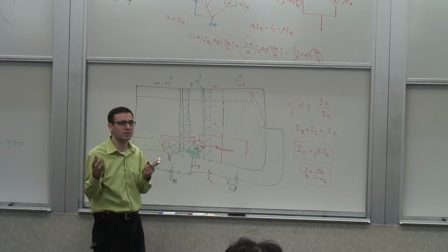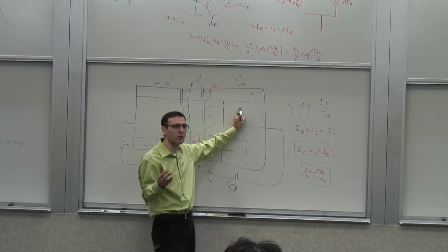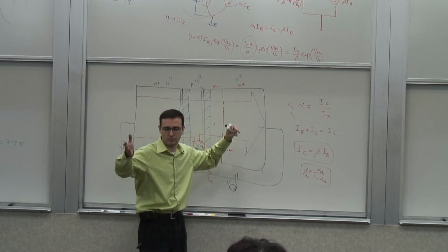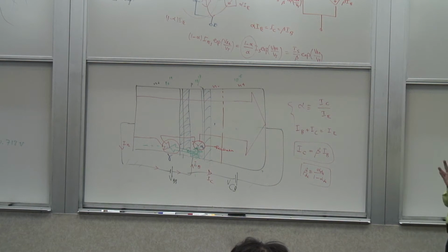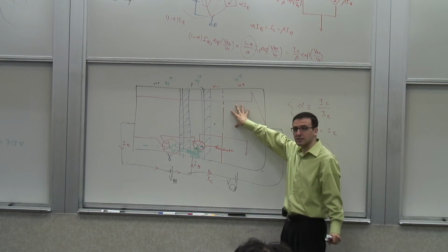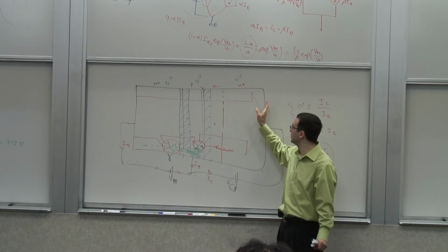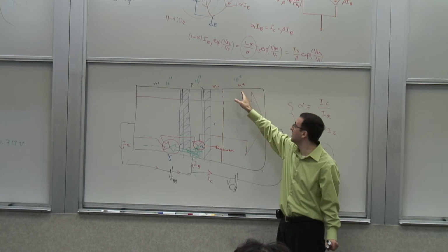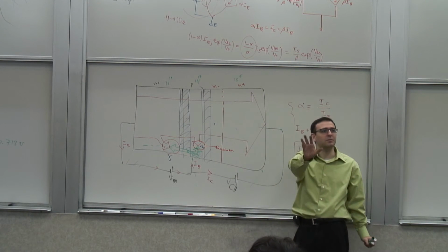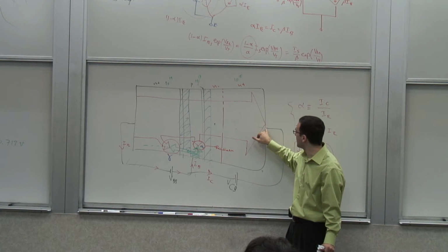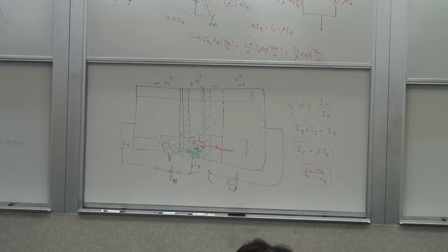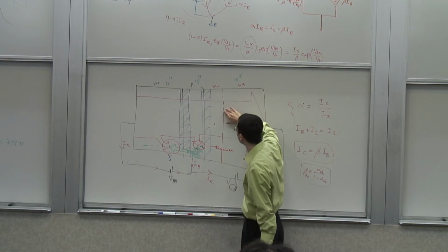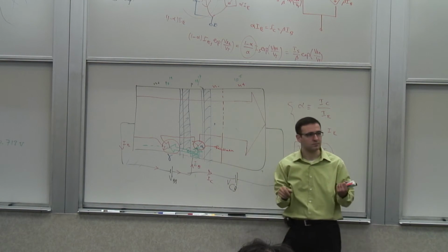So almost all bipolar transistors today have this built in one way or another. In integrated circuits, you don't need the N minus, or low doping profile, all the way. It's needed here. It also has another benefit, which is making this junction more of an ohmic contact, as opposed to a non-ohmic Schottky contact if you're not careful. You can make a diode where it should be connecting with the metal, but that's the second thing. So that's one way to improve things.